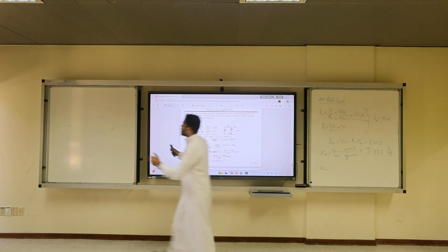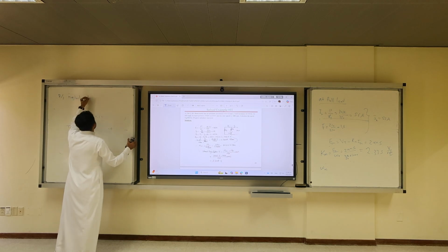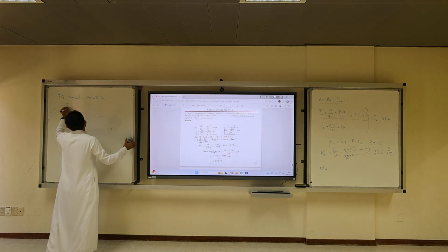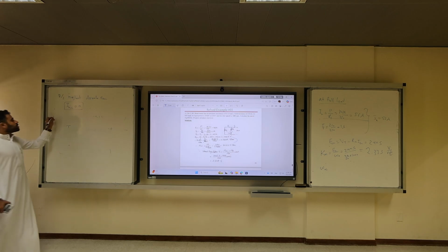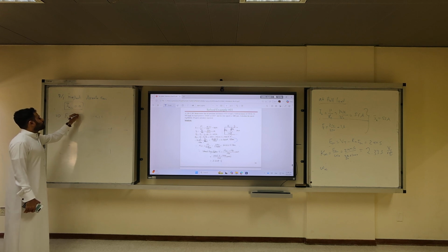So because we neglect armature reaction, IA no load equal to 0. Focus with me. This is the definition of neglect armature reaction. There is no IARA at no load. There is no rotational losses. So this implies EA equal to 250 volts.